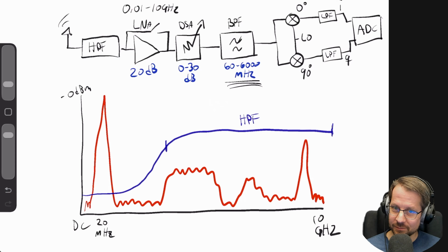High pass. That will attenuate that signal, let's say -10, -30, -60 dBm. So that will help attenuate that signal. You can get high pass filters from 1 gigahertz, high pass from 2 gigahertz. A high pass filter I use is a 2 gigahertz high pass filter, and it attenuates signals below 1 gigahertz at around 65-70 dB. That's a good one. But I can still see the signals if it's plus dB, but the attenuation is not enough to protect it, right? So that is one way to do it.